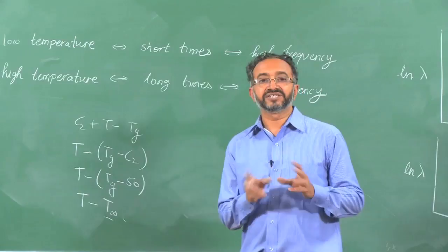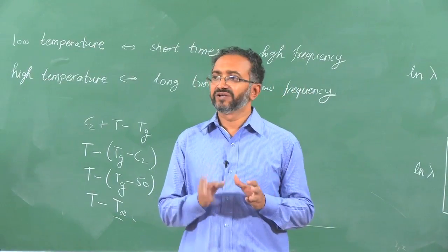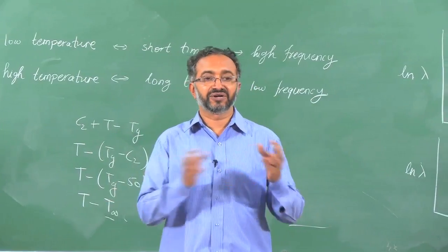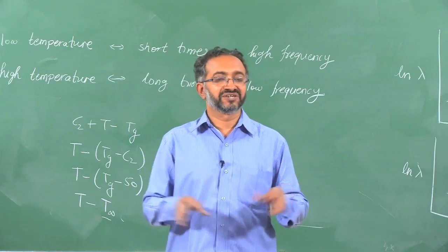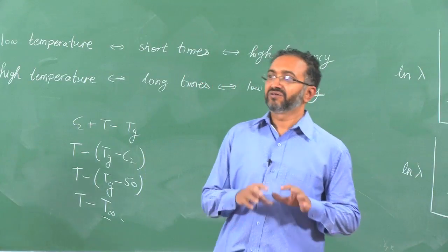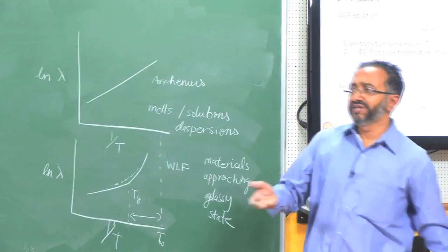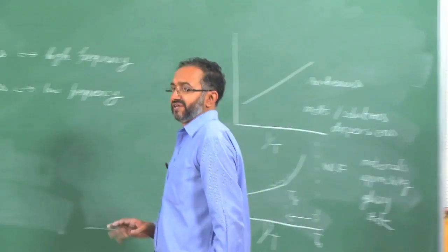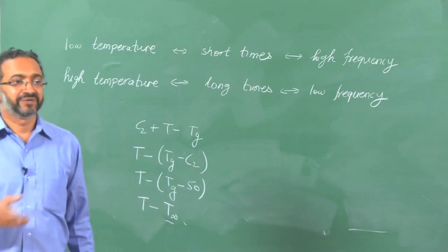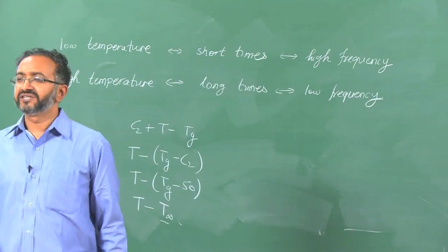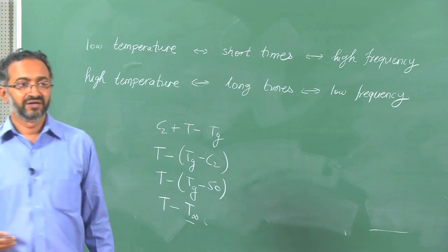And under these conditions we expect that the polymer, especially PET, will remain amorphous. So, whether it is melt state or glass state or rubber state, it is amorphous and its overall molecular structure remains identical or very similar under these circumstances. Yes, he is just pointing out that if I cool it very slowly, it is possible that it may crystallize. If I quench it, it may remain amorphous. So, the nature of crystallization in the material would depend on how fast or slow we cool it.